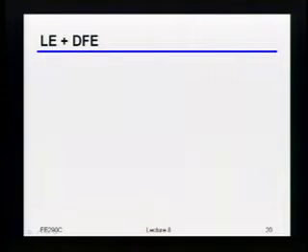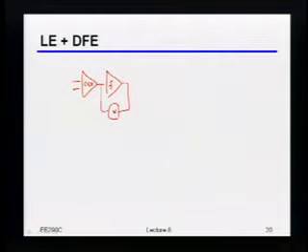So as an example, if you really have something that has, let's say, a continuous time linear equalizer plus, let's say, the DFE at least on, and I'll just draw it as single-ended to make my life easy, the DFE just on that very first tap, even that alone can actually be pretty useful. Okay? Because if you guys kind of remember from the homework, if we look at the actual channel